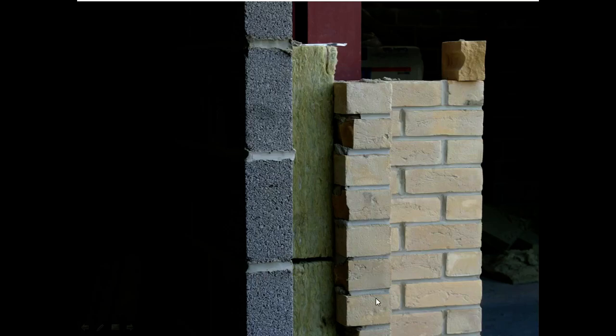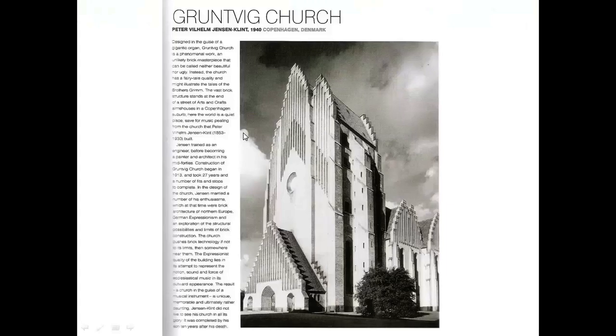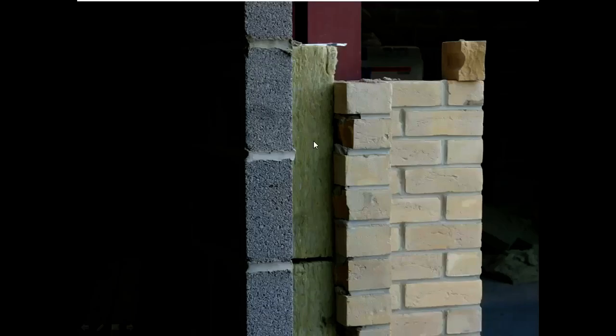So there's bricks on the outside. The inner skin is not bricks in that case. It's actually a lightweight aggregate sort of block work that's 3 bricks high. It's cheaper and easier and quicker to put together. There's the air gap, and actually in this case it's got this fibrous material which adds to the insulating quality of the wall. The inner face will then be lined with something else beautiful to make it acceptable on the inside, if you like.